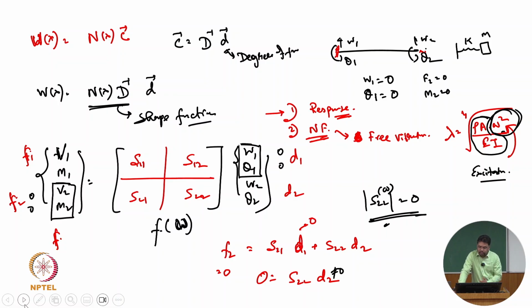So that is one of the issues that happens here. Sometimes you have to use some sort of nonlinear eigenvalue solution, a Newton-Raphson type technique, or bisection, this type of technique you can follow. But still, once you are solving for omega, if the omega value is real, that means there is no damping.